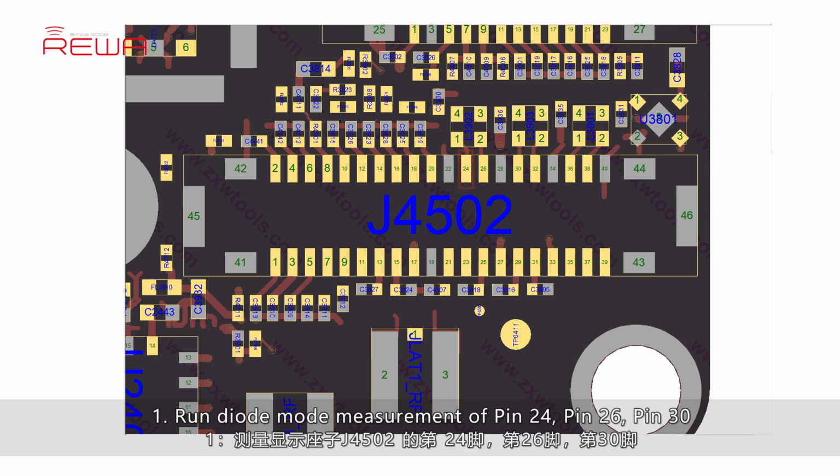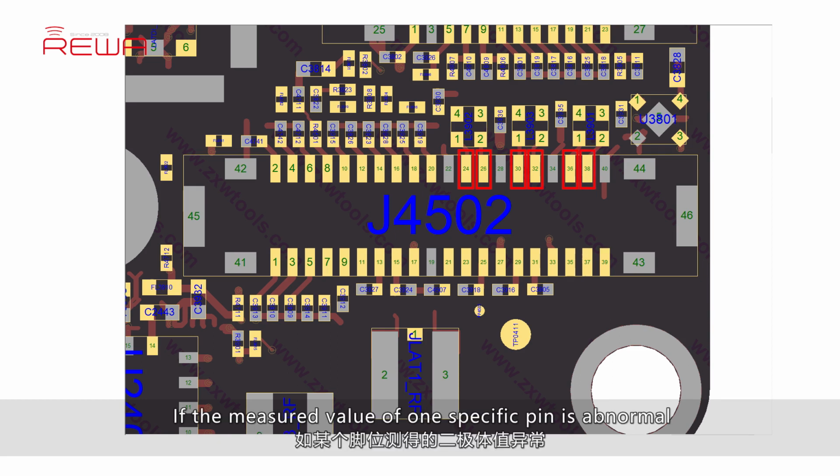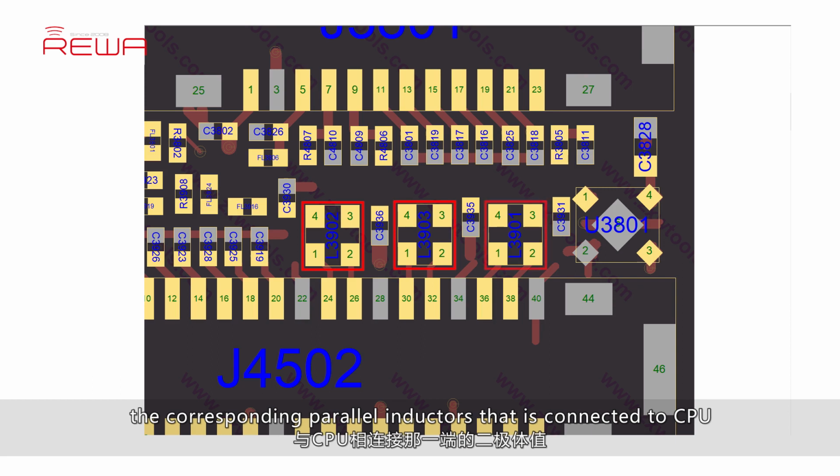1. Run diode mode measurement of pin 24, pin 26, pin 30, pin 32, pin 36 and pin 38 of J4502. If the measured value of one specific pin is abnormal, run diode mode measurement of the specific end of the corresponding parallel inductors that is connected to CPU.